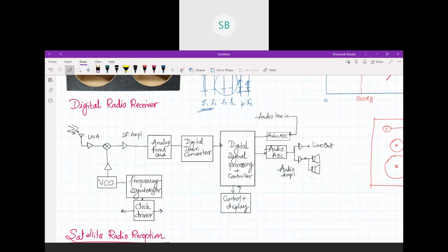Some systems make use of a single frequency network, SFN as we generally call it, in which all the transmitters in one region which transmit the same multiplex signal may use the same frequency without interference to each other. And the major advantage is that this will improve the spectral efficiency of the system, because as we have seen earlier, one of the costliest things is the frequency.